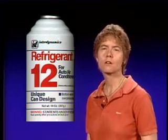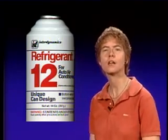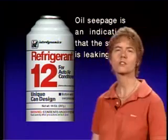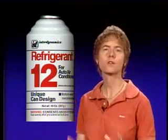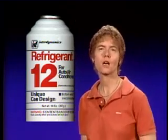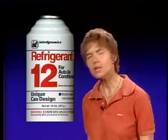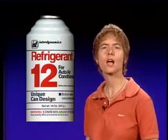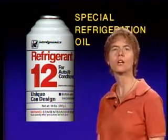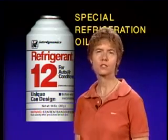Now, when a vapor cycle cooling system is not in operation, one of the ways to tell whether it's leaking or not is to look for oil seepage. Oil seepage is an indication the system is leaking Freon. You will not see the Freon itself because the Freon is colorless. But the oil is contained in the Freon, and if you see oil seepage, you know that you've had some Freon leakage. When you need to put oil back in the system, what you have to use is special refrigeration oil. Special refrigeration oil is the only oil that's suitable for use in Freon air conditioning systems.